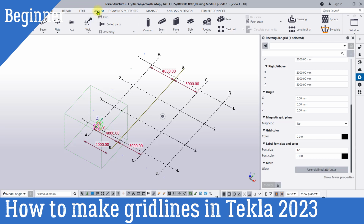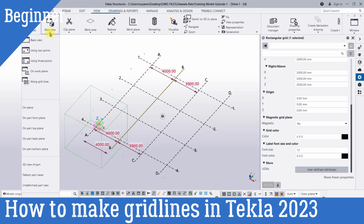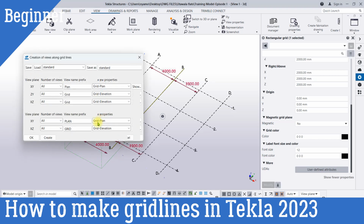So I'm going to go to view, then I'll go to new view, click there, and if you go down you'll find that there is a drop down on along grid lines, which means create view along grid lines. So I will hit that. It should take me to the same wizard, just like when I was right clicking to create a new view. So this one I'll just hit OK.